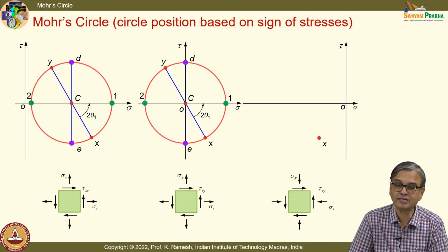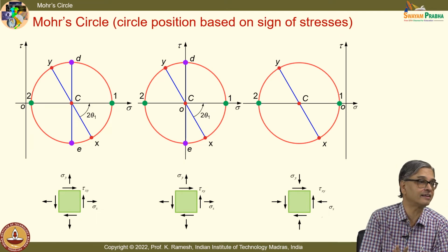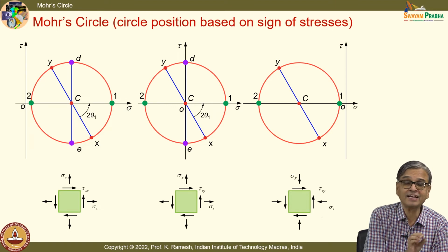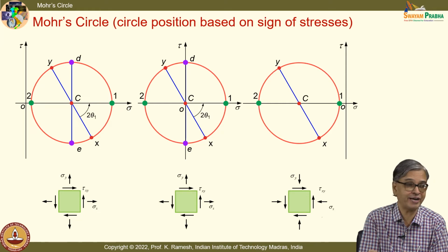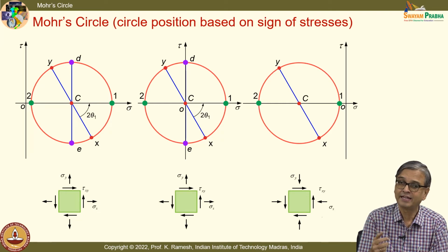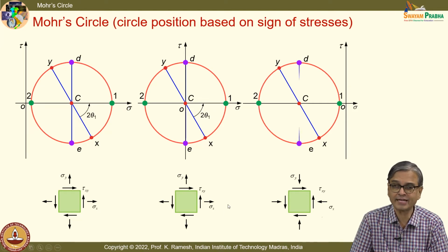I can also have a Mohr circle like this. So, what you will have to appreciate is the graphical representation remains a circle, its location can get shifted. In a special case, it can become a point, fine. And you will have to carefully identify what is the x plane and y plane on the given Mohr circle, or for a given stress state, you first locate the x and y plane, then plot them. So, that is the message in this slide.